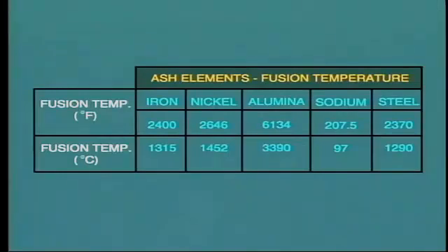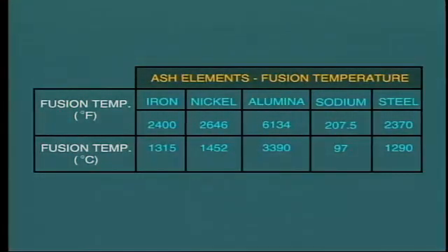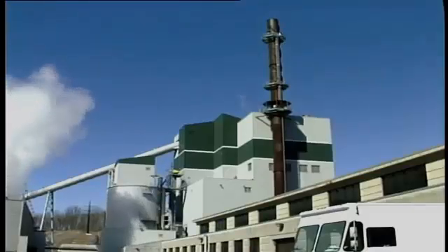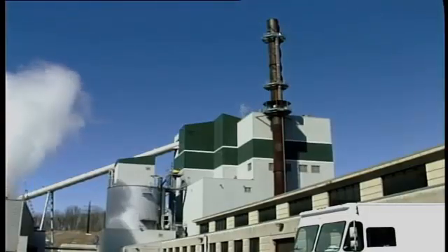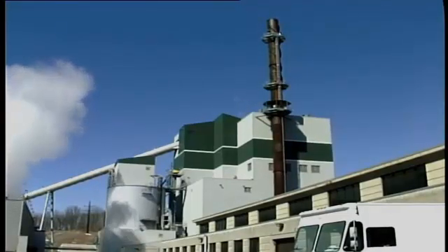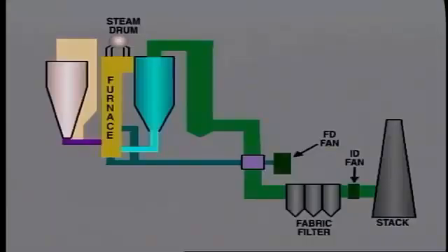This lower combustion temperature has several advantages, especially when burning poor quality fuel. One is that the combustion temperature is well below the fusion temperature of most components of ash, so eliminating most of the slagging problems that are common with many low-grade fuels. This type of combustion is also more environmentally friendly, as we shall see in our discussion of this subject in the next module. Let's take a closer look at a typical design.